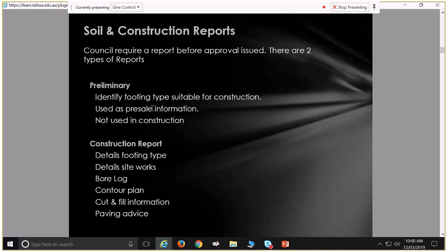So around that French drain or that ag drain, you pile lots of aggregate as well to allow moisture to seep through there into the drain. But we can also use such things around buildings as well. So to get rid of moisture around a building, you're not allowed to use an ag drain within 1 metre of a building because it can actually deposit moisture from one place along its length as well. So you have to keep them 1 metre away from buildings, but to ensure that you don't get terrestrial and sometimes subterranean water flows toward a building, you direct it away from that building with things like a subterranean ag drain.